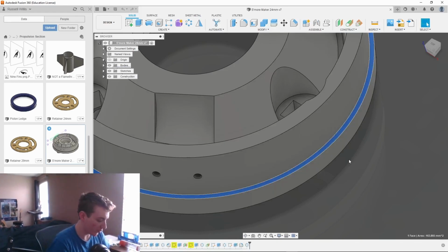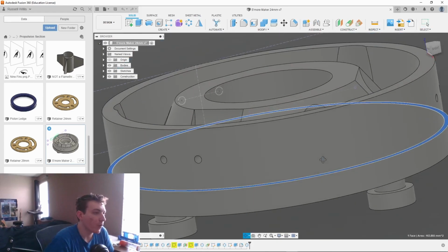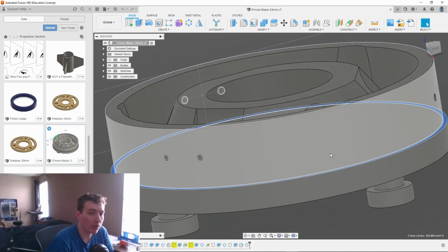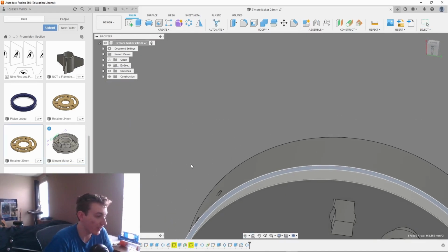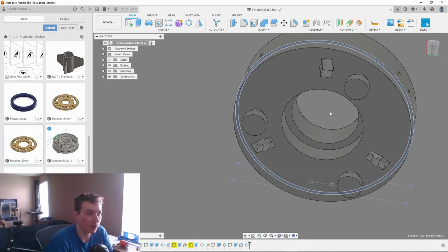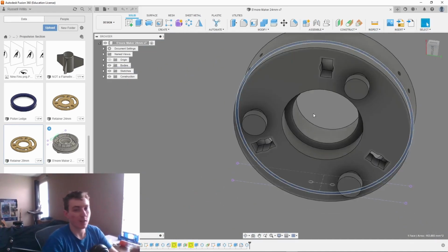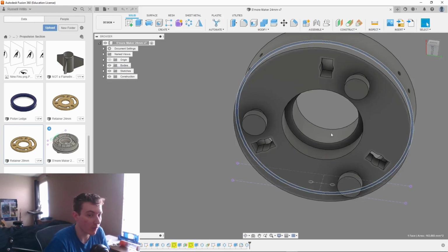Then when we get to around apogee, the ejection charge fires. And the ejection charge is going to want to shove the motor right out the bottom, which is real bad. So we've done one of two things. We've had a retainer. You can see a retainer right here. It would get slotted on this hardware right here. It's a little complex. It would make it so the motor can't go any further because it would bump into the retainer.